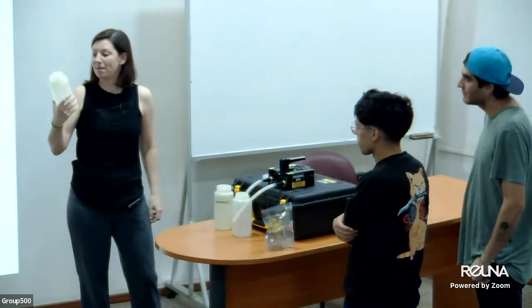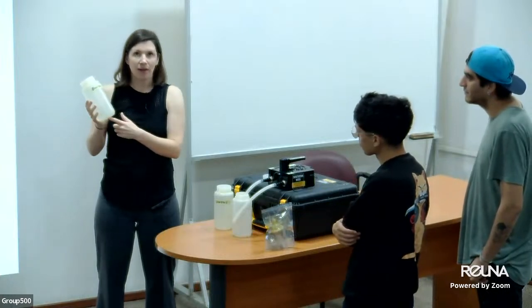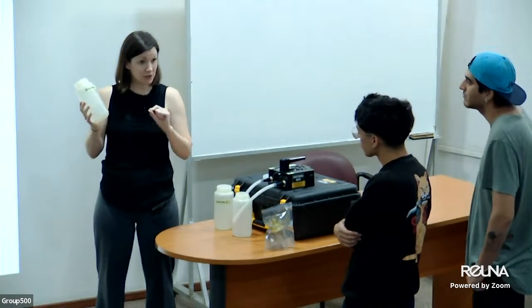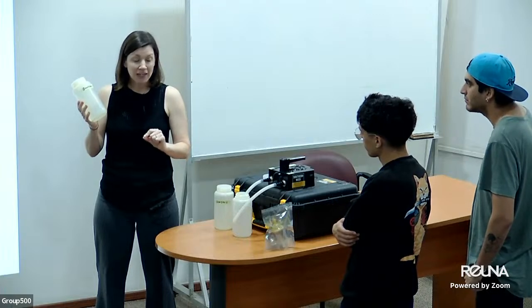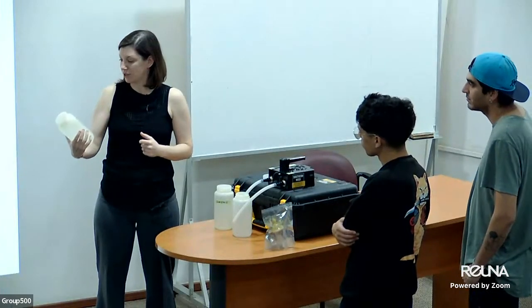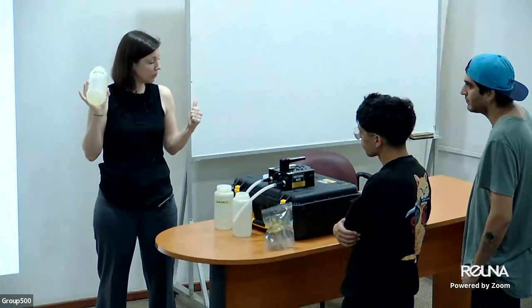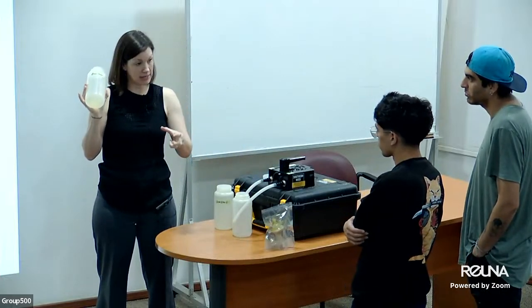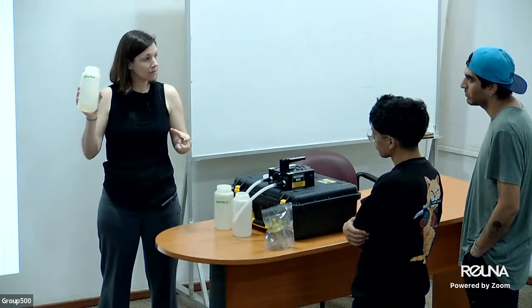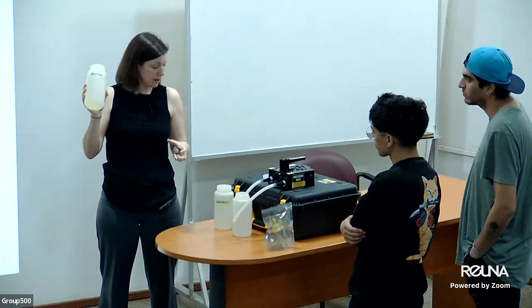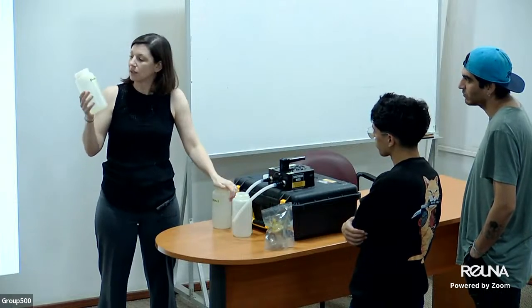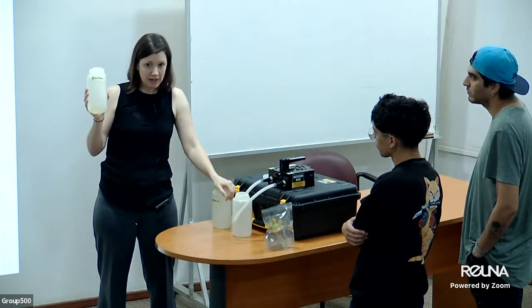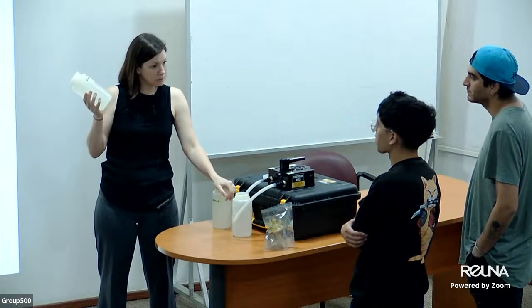Yep. The first thing I need to know is what volume, what pore size. Because again, remember, I want the smallest pore size possible. So the first thing I always do when I get to a new site is I do a test. Just by looking at this, I brought 0.45 and I brought 5 micron pore sizes. I know this is way too clear for 5. So I have 2 samples and we'll do it with 0.45, and I think that's going to be good. If it goes super fast, then 0.22 might even be okay.